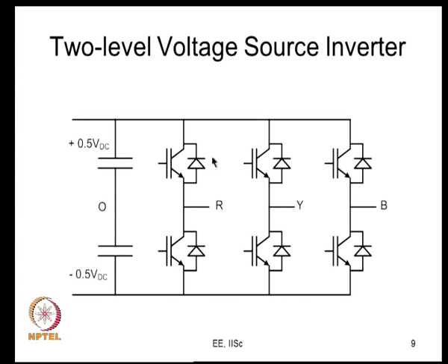Let us get started. So, this is the inverter. Now, you have two legs which are switched in a complementary fashion, and we are going to ignore dead time today once again, like we did for the analysis of linear modulation, because our focus here is understanding the difference between linear modulation and overmodulation. Alright, and there is a 3-phase load, we can presume it to be maybe an induction motor. So, we are going to look at these basic quantities, so it is better that we take a quick recap of that.